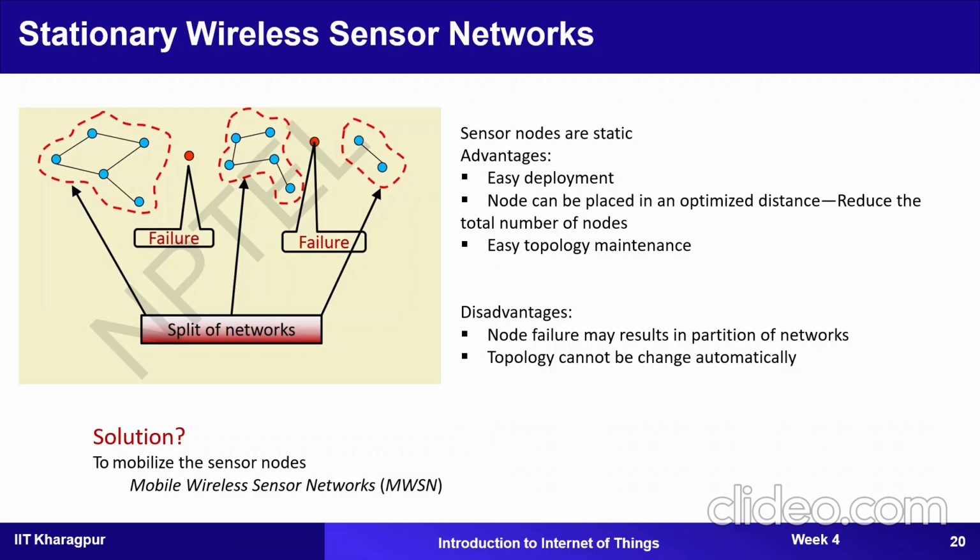Okay, what is coverage and what is connectivity? Coverage is how much the sensors can detect from the area, and connectivity is whether these different nodes can communicate with each other. So coverage range is less or connectivity range of a particular sensor is less? The range at which they can transmit is usually higher. No. I'm asking whether the point till which a sensor can sense the data is less, or till what point it can send the data is less. The sensing range is lesser. Okay. So correct option for this is coverage implies connectivity.